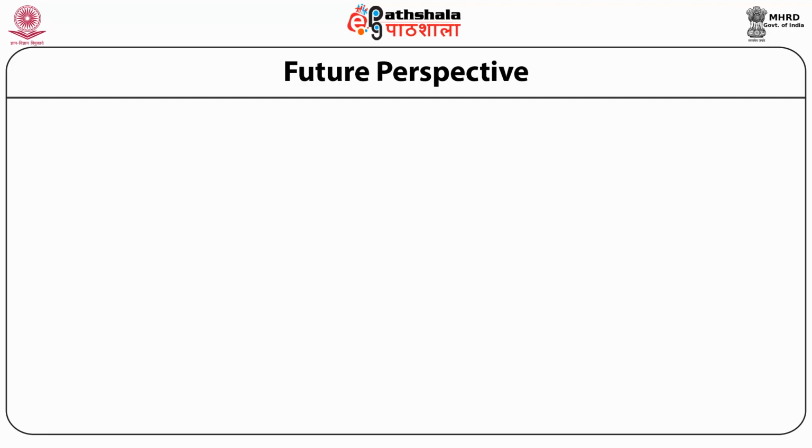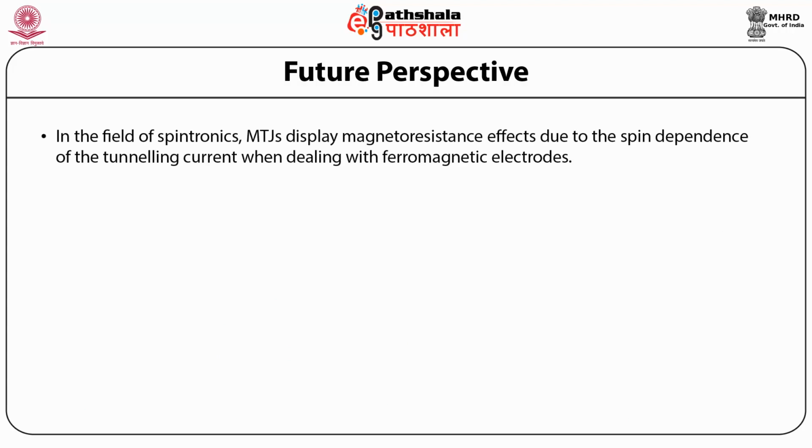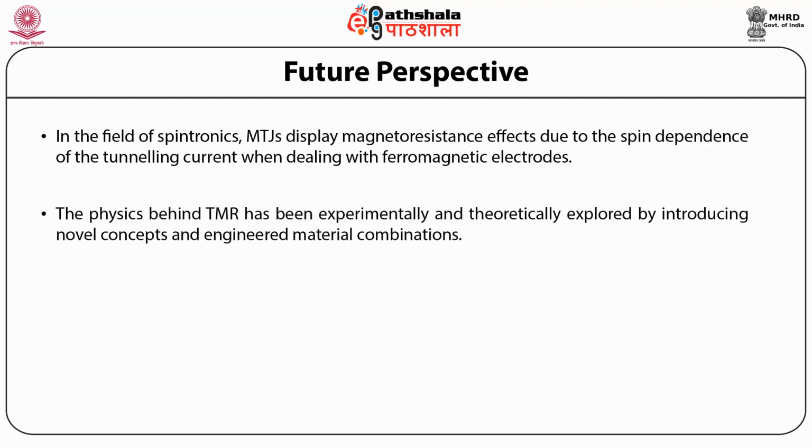Let us talk about the future perspective. In the field of spintronics, MTJs display magnetoresistance effect due to the spin dependence of the tunneling current when dealing with ferromagnetic electrodes. The physics behind TMR has been experimentally and theoretically explored by introducing novel concepts and engineered material combinations.